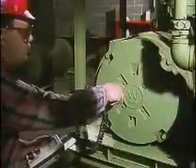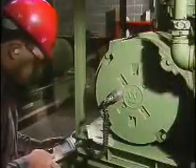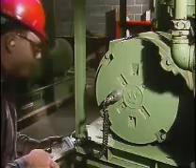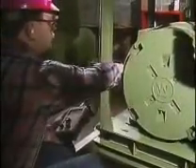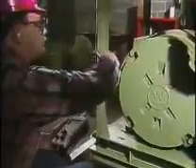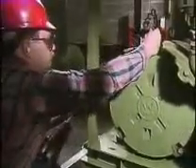On a machine with a horizontal shaft, the bearings would also be checked from an axial direction and from 2 radial directions. Typically, one radial measurement is taken horizontally and the other is taken vertically.